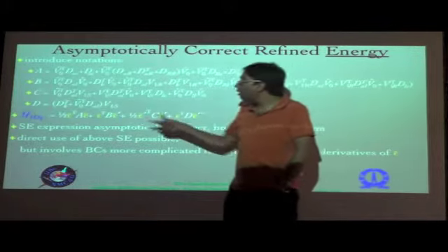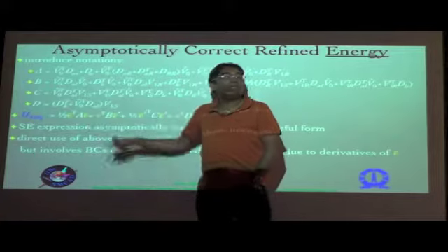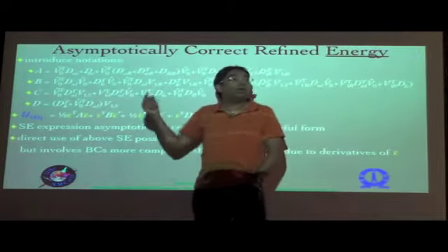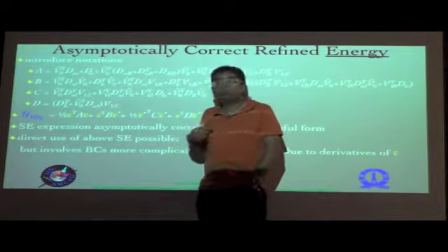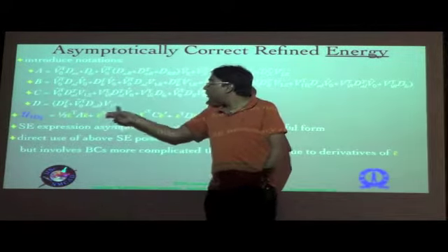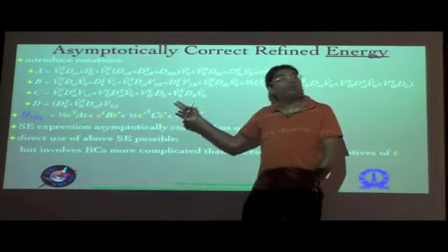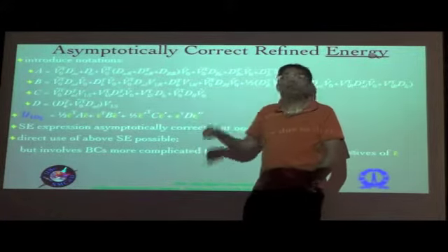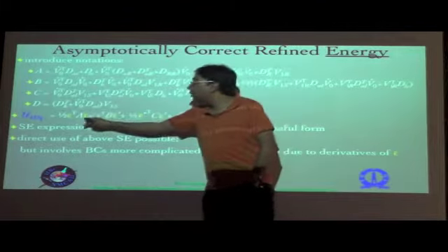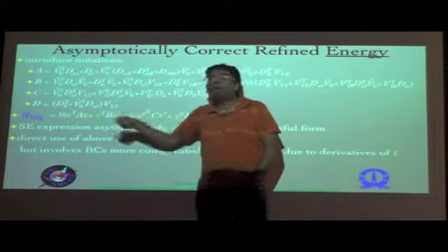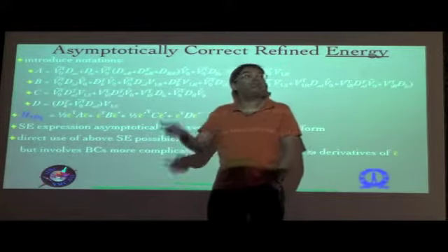Instead, it involves, instead of 4 variables here, 6 variables, by introducing 2 additional variables, 2 gamma 1 2 and 2 gamma 1 3, the transverse shear strain measures. So, is there a way that we can force this into that particular form, involving not only the epsilon bars but also the 2 gamma 1 2 and 2 gamma 1 3? And again, epsilon bar itself might take a different meaning once you go there.